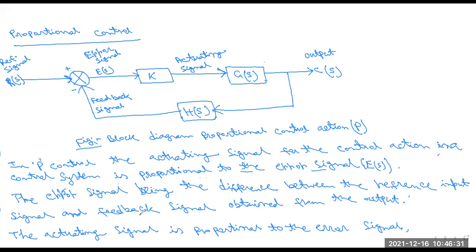Desirably, the control system is under damped. We know about under damped, over damped and the damping factor from our previous classes. This under damped control system exhibits exponentially decaying oscillation in the output time response during the transient period.